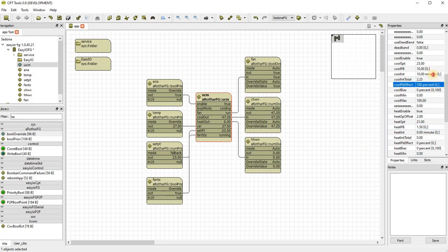Let's let this wind up for a bit. Let's drop this down to 1 minute. Again, it helps get some integral component into the loop. Let's set this to 0.1. There's no way to manually change this. You have to mess with the integral value to get the integral to wind up. So every 6 seconds.